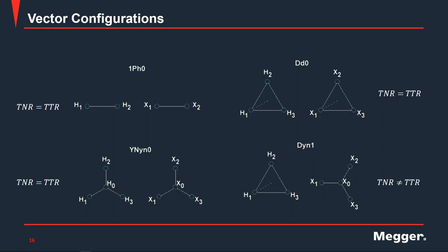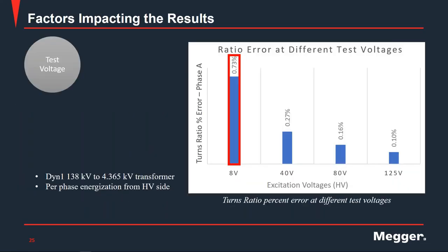Okay, interesting question. There is no rule written in the standards or recommendations based on the nameplate of the transformer you're testing. Just make sure you're applying a high enough voltage to be able to induce voltage on the other side of the transformer. And also remember the aspects that Ken touched on in his presentation in regards to doing step up versus step down. That will be more important. And again, no written rules.